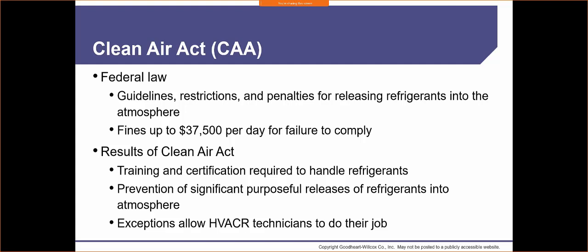Back in the day, it would just be the hose. As soon as you undid the hose, all the refrigerant would just leak out. So now there's one-way valves on there, so the refrigerant stays inside your hoses, or there's little ball valves. I personally like the little ball valves, easier. I can open, close, do a little bit more as opposed to just the one-way type.